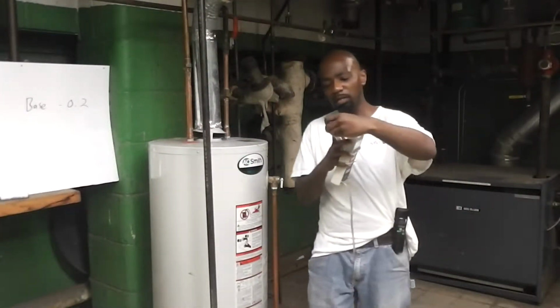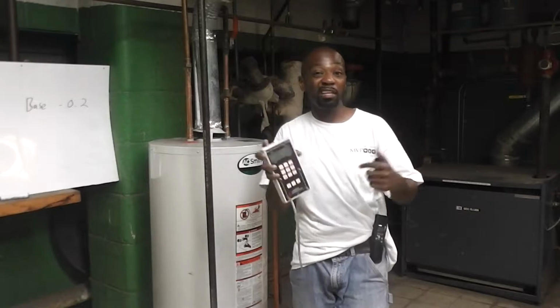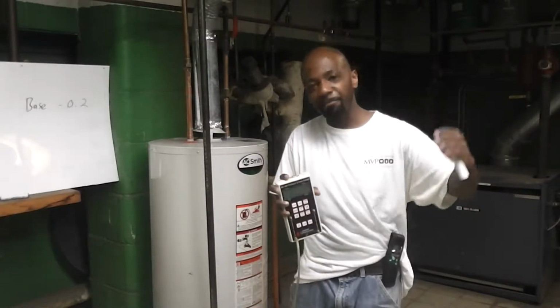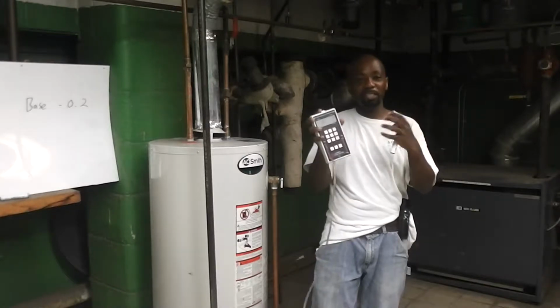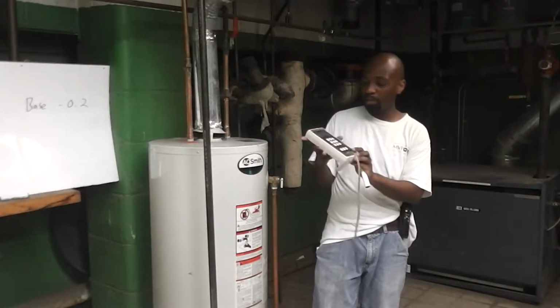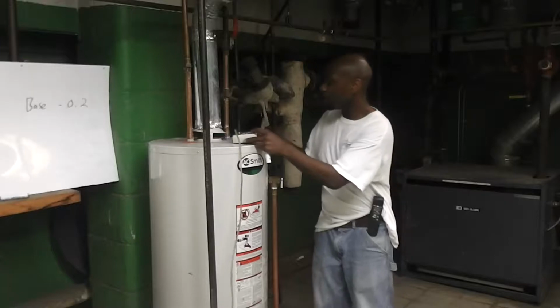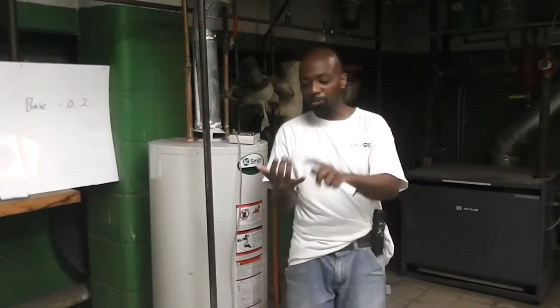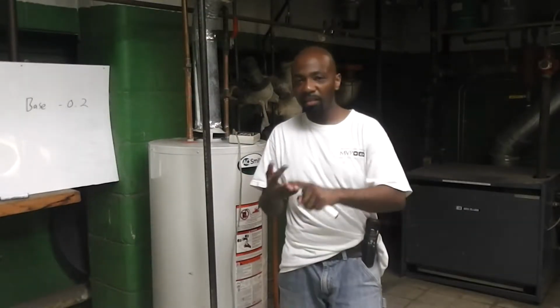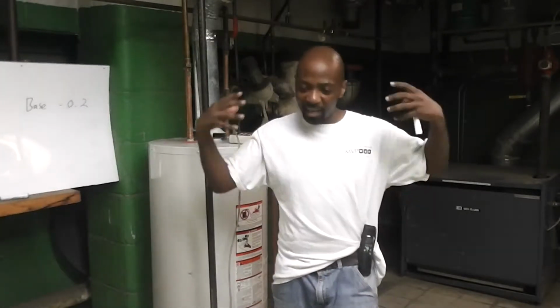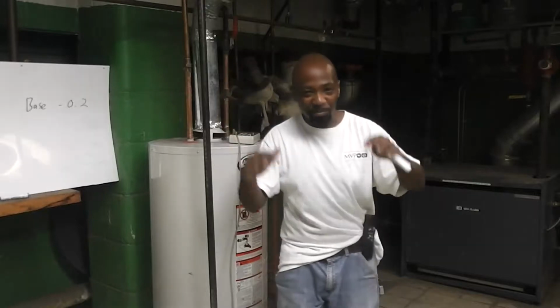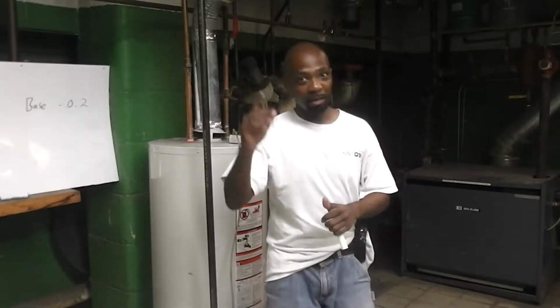Now I want to set up the house in the worst case. I want to make this house as negative as possible, and take into account how the pressure in here changes. I'm going to put this down for a second and go around and make sure all the dryers, all the exhaust fans, anything that makes this place more negative, including other rooms inside the house, is sucking air out of this place, making it as depressurized as possible. I'm going to do that right now.